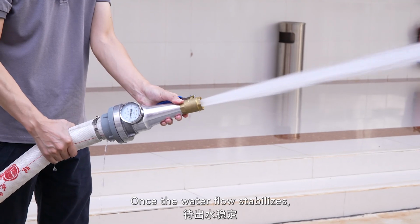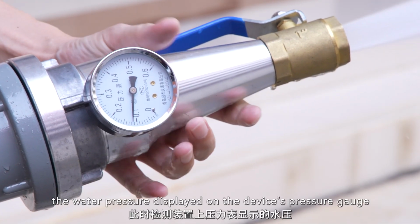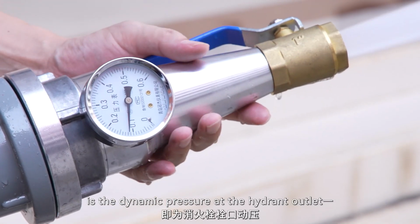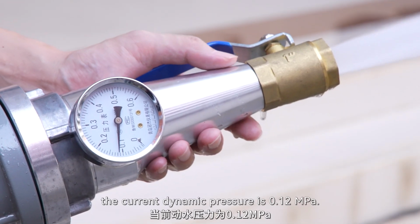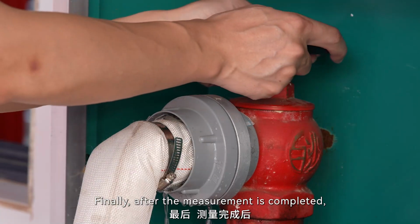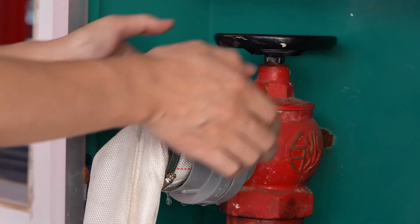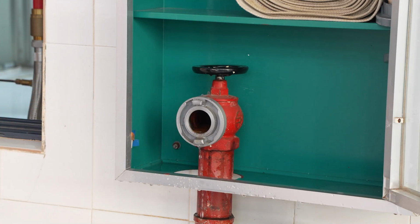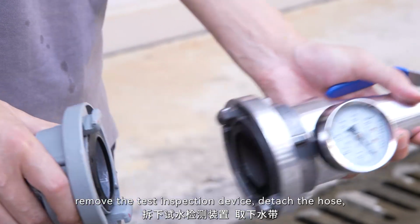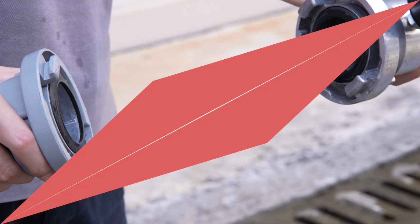Once the water flow stabilizes, the water pressure displayed on the device's pressure gauge is the dynamic pressure at the hydrant outlet. The current dynamic pressure is 0.12 megapascal. Finally, after the measurement is completed, close the fire hydrant valve. Remove the test inspection device. Detach the hose and drain any remaining water from the hose so that it can be air-dried.